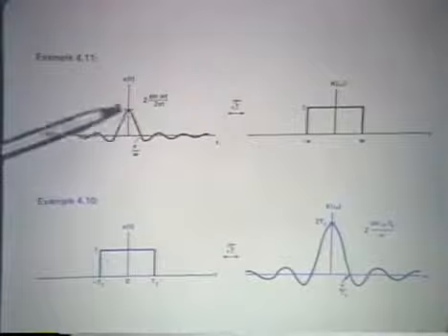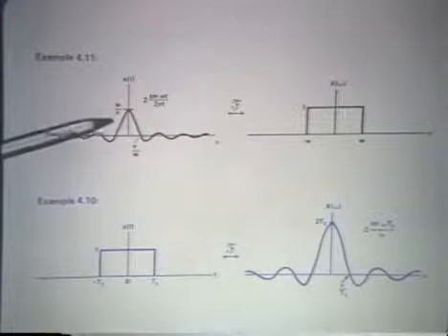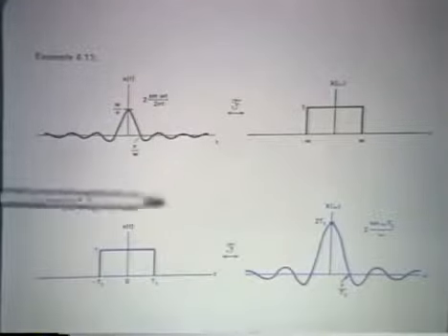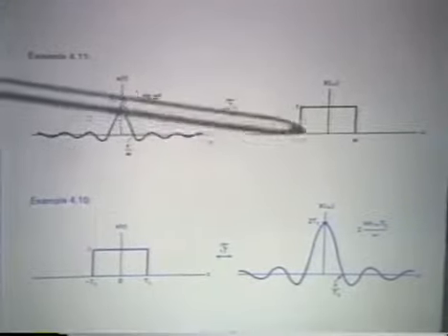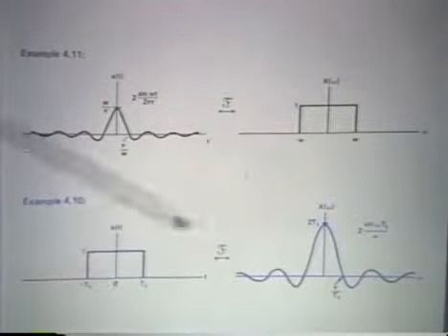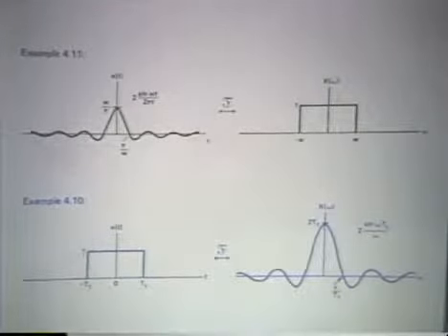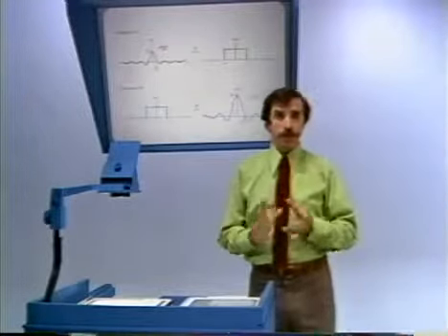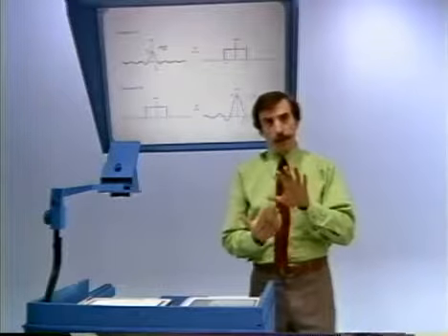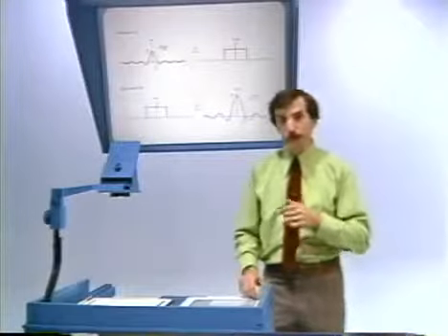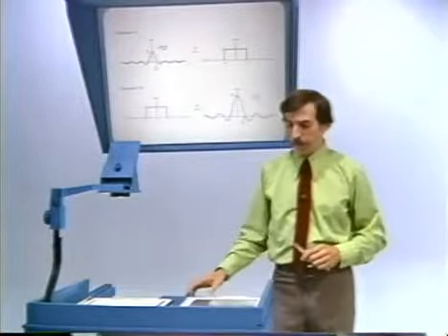In other words, if we take this time function and instead think of a frequency function that has the same form, then we simply interchange the roles of time and frequency in the other domains. So the fact that these two correspond means that these two correspond. Of course, in this particular example, because of the fact that we picked a symmetric function, even function, in fact, the additional twist of the time axis being reversed didn't show up in duality with this example.